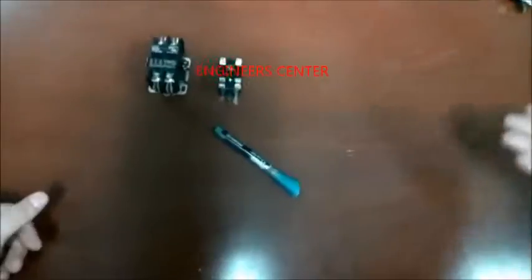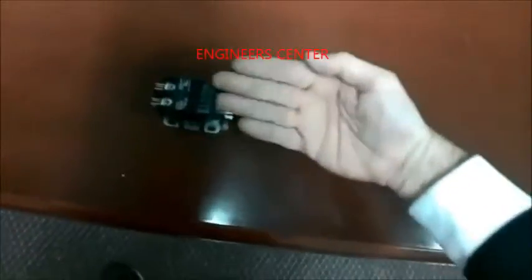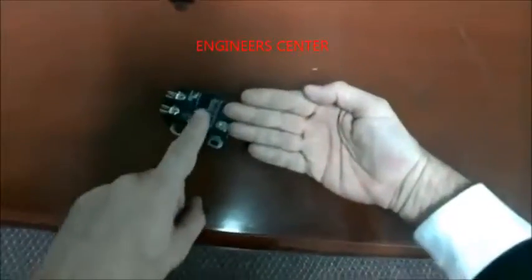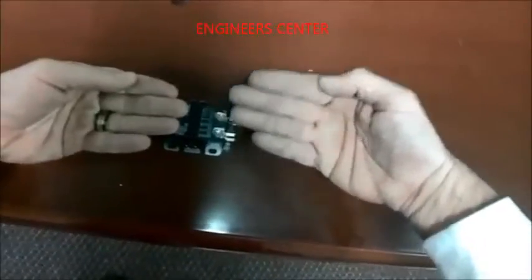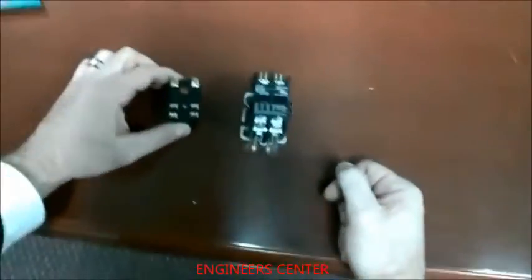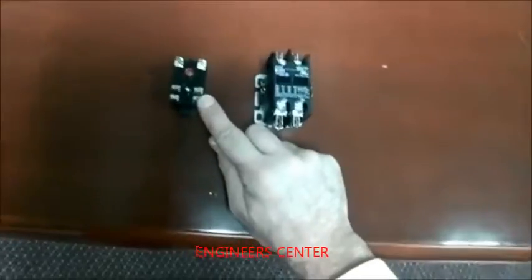And so if you have power coming in to this from your breaker and it's open, your compressor and your contactor are all wired here, but as soon as this closes, power is bridged across and sending power to all of your parts. Therefore, closed means bridging power across. And so this and this do the same thing. You would have power going in, and this would go to your parts, whatever you had this wired off of. And these are both controlled.